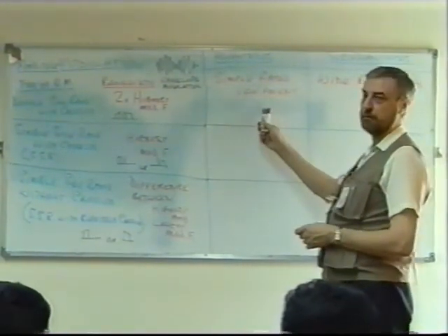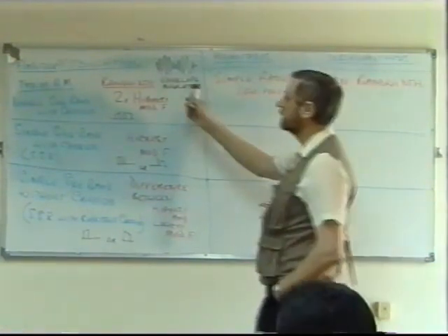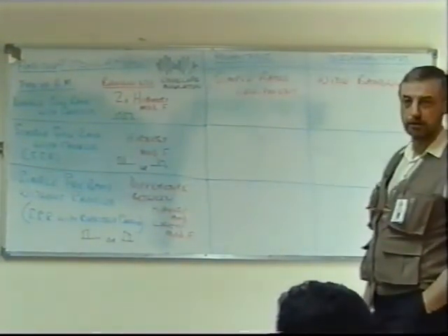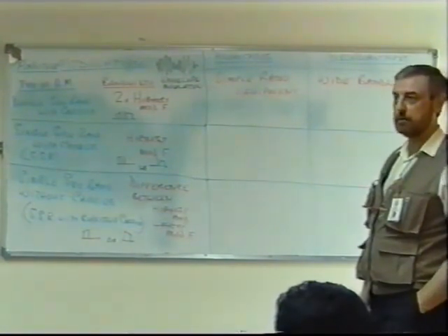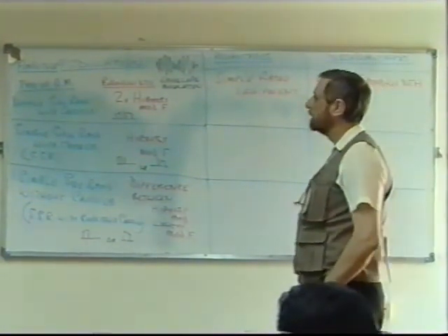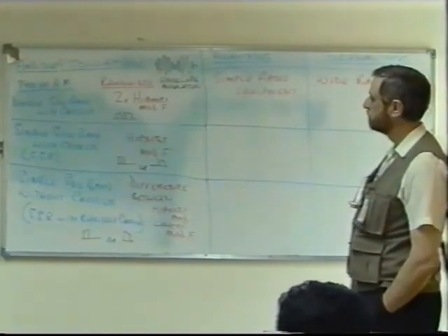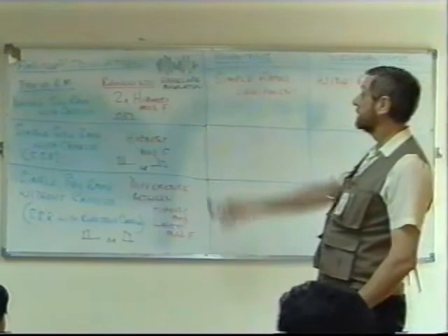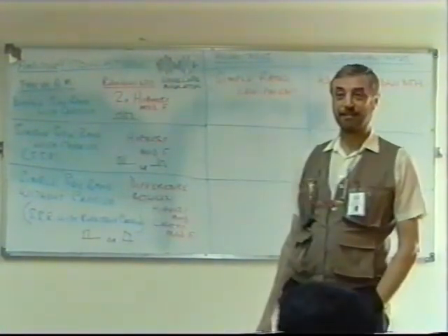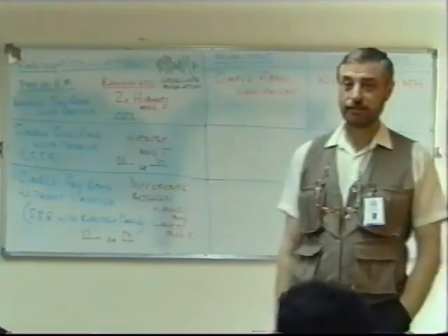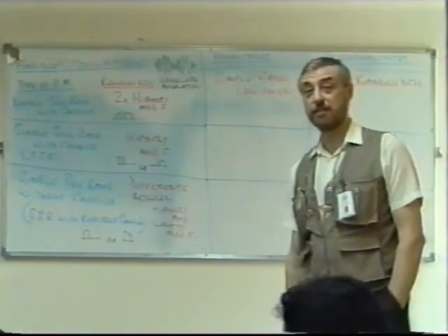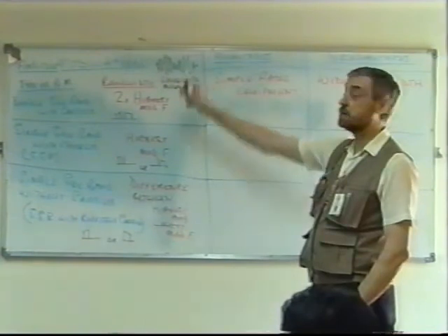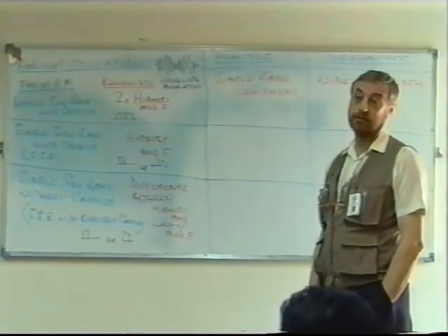But otherwise, very simple. In fact, all you really need to demodulate this is a simple diode, that's all. If any of you have ever experimented with simple radio receivers. You cut the signal? That's right, it's like half-wave rectification, isn't it? Yeah, that's right. It's like half-wave rectification, or you can even have full. That's exactly what it is. A simple diode will demodulate that and give you the audio.